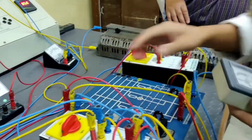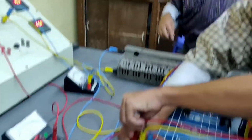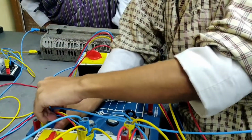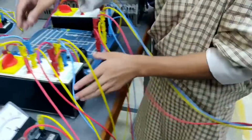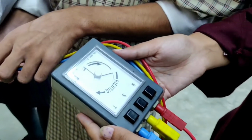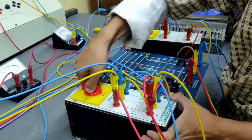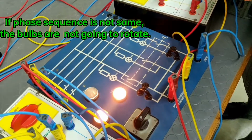Check the phase sequence of the voltage generator. We used a phase sequence meter. The direction of motion for both should match. For our case it was both in the anti-clockwise direction. From there we confirm that it has the same phase sequence.